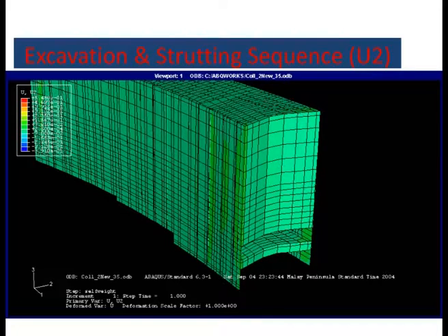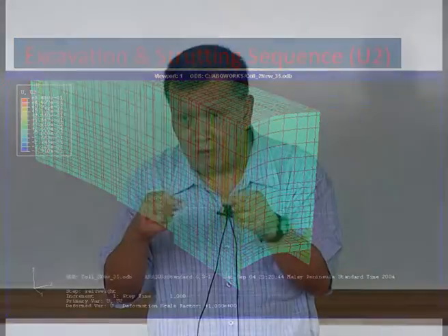The diaphragm wall panels I mentioned to you yesterday: every panel is cast with a concrete key, but there's no steel in between, so the panels can easily break up. To allow the panel to break, we modeled every individual panel of the diaphragm wall separately, without common nodes, but with two separate nodes. Between the two separate nodes, we put in a linkage element. This special linkage element will break when the strain exceeds 0.1%, which is the fracture strain of the concrete. So that allows the wall panel to break up.